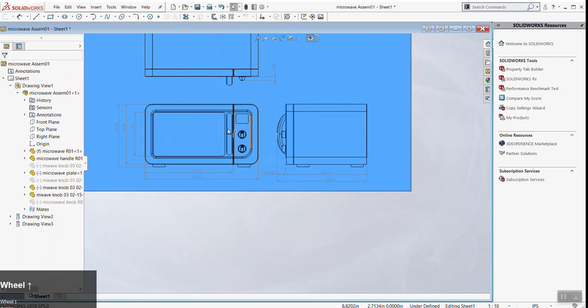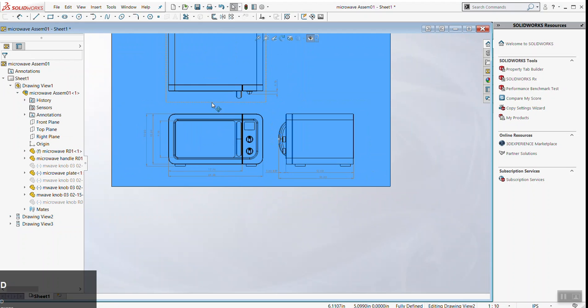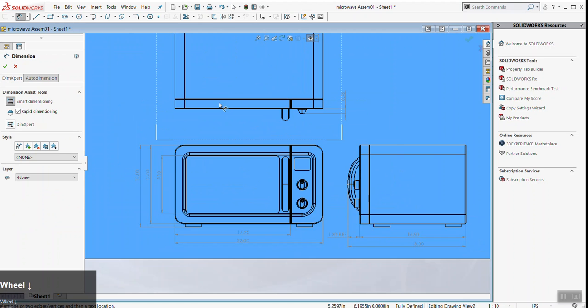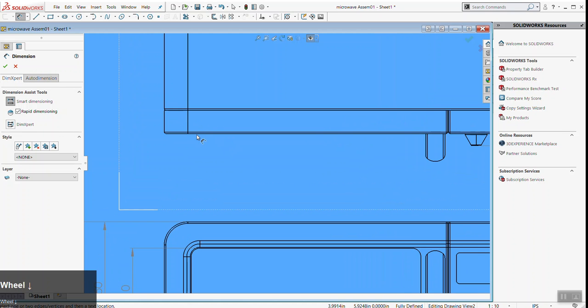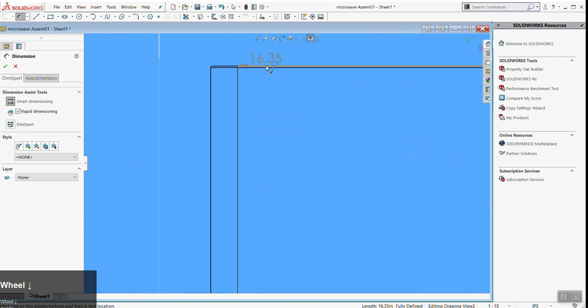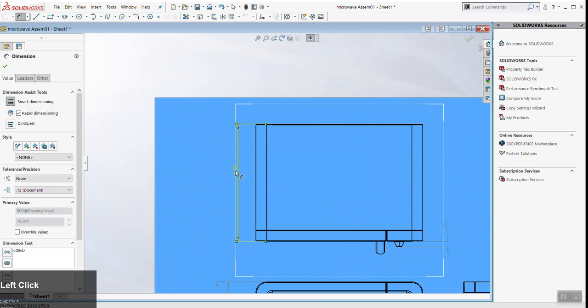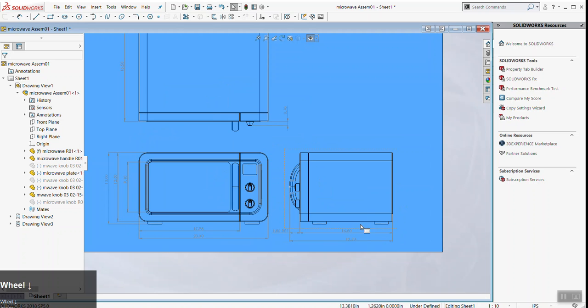Here's another, and again, we're totally in the weeds, but I just want to arm you with full knowledge. If I dimension this view here, front to back, this is also repetitive. The 16.5 here is also down here. And again, it's all in the name of clarity. It's all to let whoever's looking at this know this is the most important dimension. When there's too much information or, God forbid, conflicting information, that's when you have a problem.